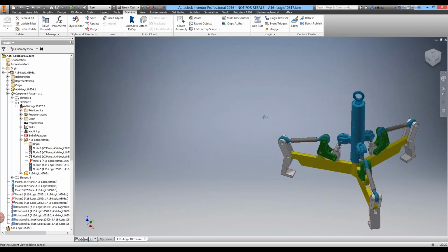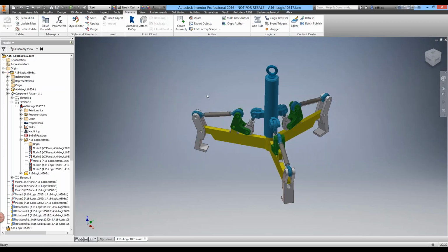Okay, cool. So far we've just identified each of those parameters, and we've also created a driving parameter at the very top level. As you can see in my browser over here, these components are quite low level, so I'm able to access the parameters straight down the tree without having to go through any complex loops. iLogic allows me to directly change parameters all the way down with immediacy.